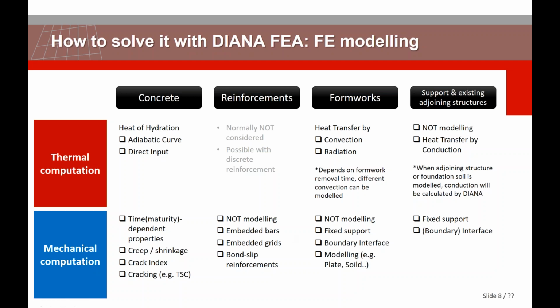As far as I know, when we start early age concrete cracking analysis using the finite element method, and still in practice, engineers try to reduce the analysis time and modeling time, and they just model plain concrete instead of reinforced concrete, and then they run the analysis. But these days, modeling of reinforcement is not that difficult. It's very easy. Maybe at the end of my presentation, I can also show you how to do that.